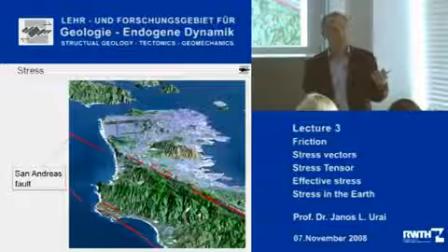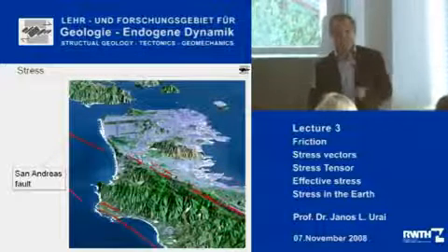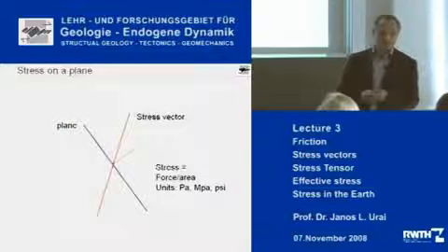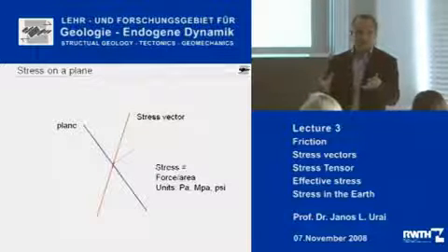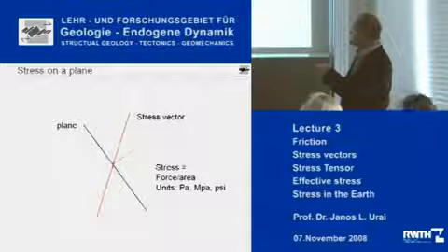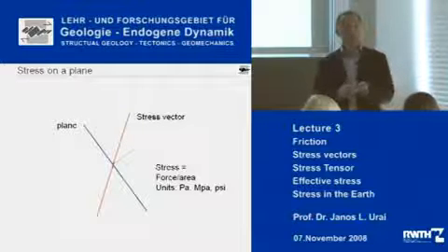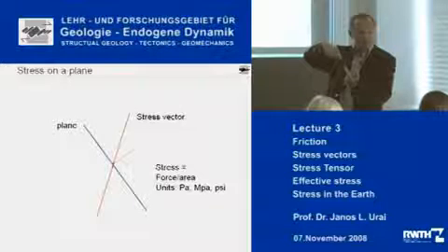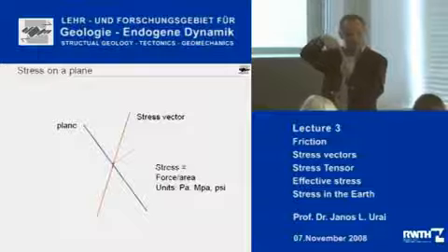Just like with strain, if you want to start understanding stress a little bit, you have to go back to very, very first simple principles. So we will start with the stress vector. Okay? The stress vector is something which is defined in mechanics. It is a pair of stresses which act in opposite directions and in equal magnitude across a plane. You could say that the stress is built up from the forces which act on this plane. Of course, for the equilibrium, you need to have these exactly opposite.